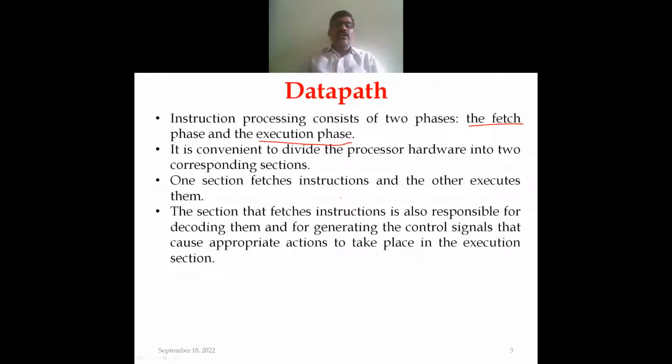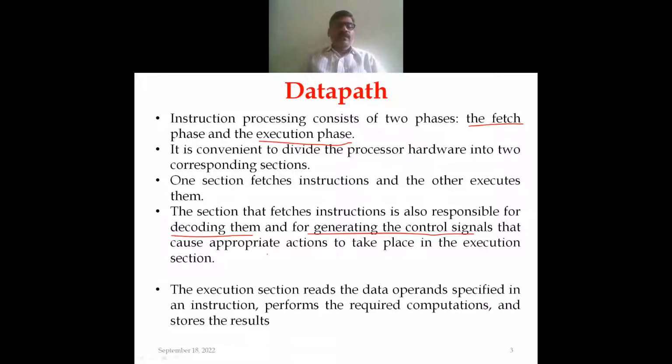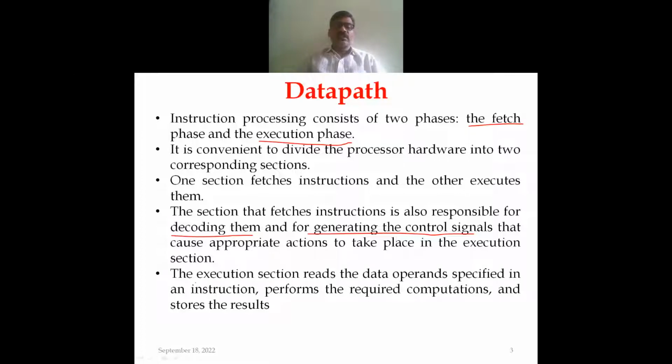The section of the hardware which fetches the instructions is also responsible for decoding that instruction and generating the control signals that cause the appropriate actions to take place in the execution of the instruction. The execution section will read the data operands specified in an instruction, then perform the required computation and store the results.